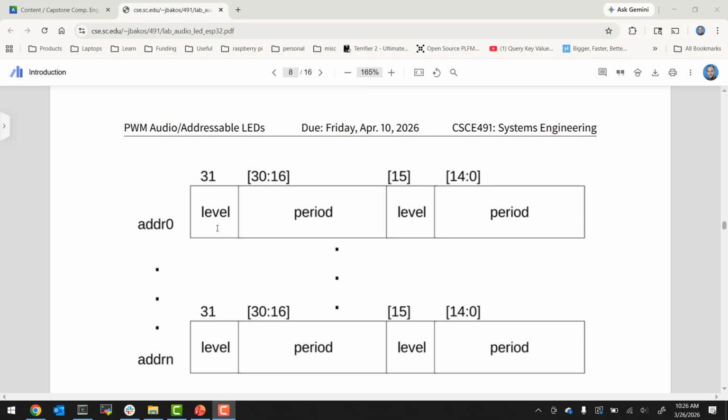The problem is they don't have 2,400 entries in here. There's only 384. So as a result of that limitation, you have to write one color at a time, wait for it to finish sending that color, and then go back and update this array again and tell it to go again, right? I was going to say you can update the array while it's sending, but actually I don't think you can do that, because if you update the array while it's transmitting, you'll probably bork it, right?